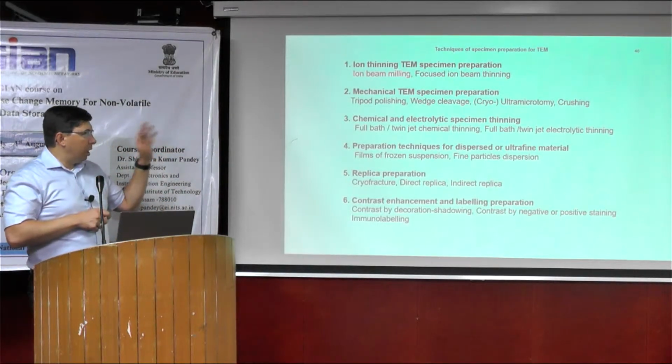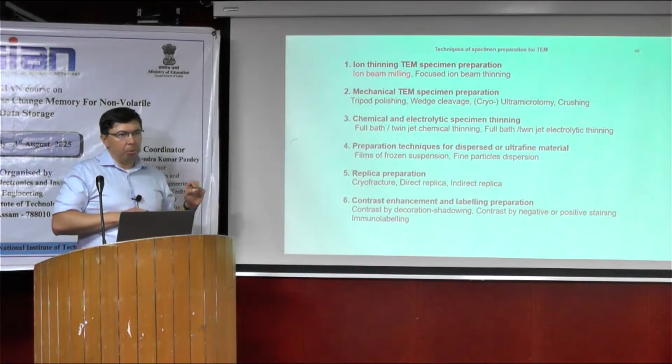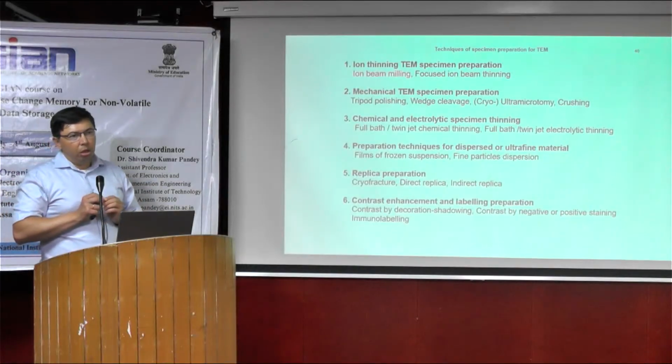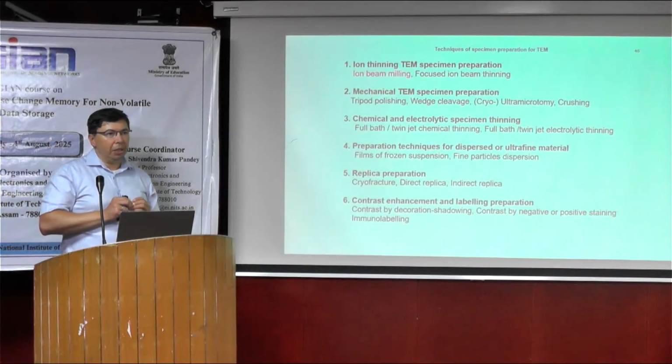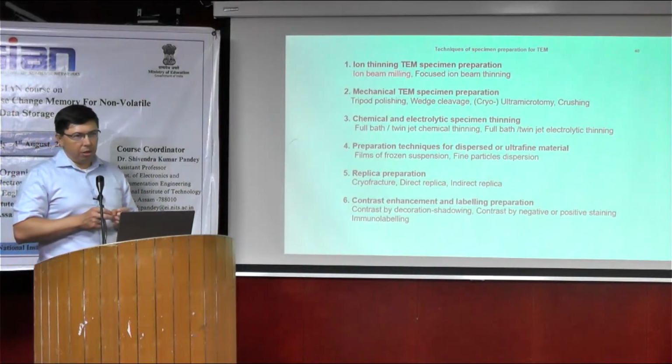But there are also some issues with mechanical specimen preparation. Sometimes the material can be mechanically unstable, or during this mechanical polishing you can bring some stresses into the system or even damage it.